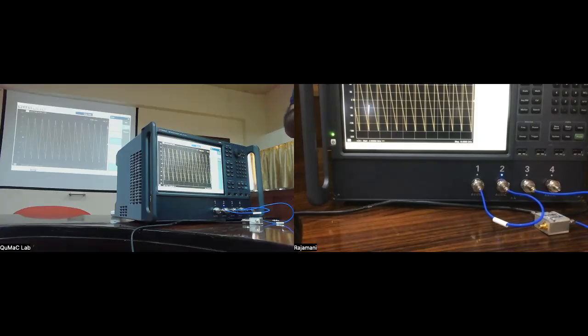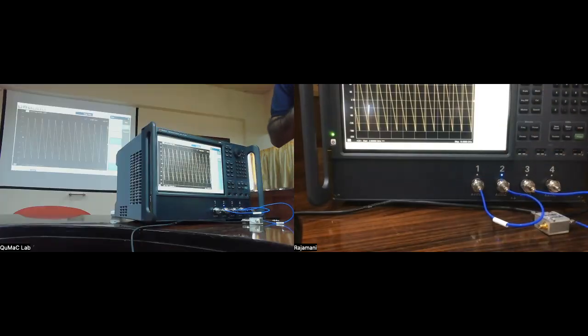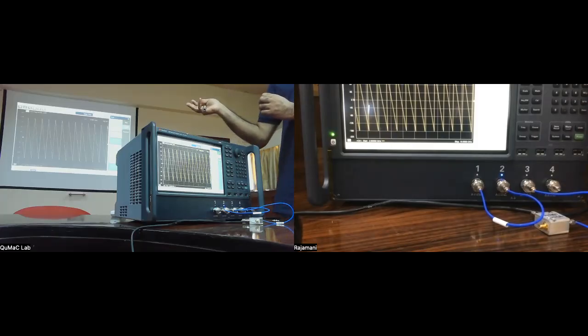Yes, of course. But when we are making the system, it would be frequency dependent. Okay. Well, in most cases, you don't expect the velocity to be frequency dependent. You mostly don't study dispersive systems. But remember that we are only cancelling out the effect of a coaxial cable. A coaxial cable should not be dispersive. If your actual device is dispersive, that you will see.